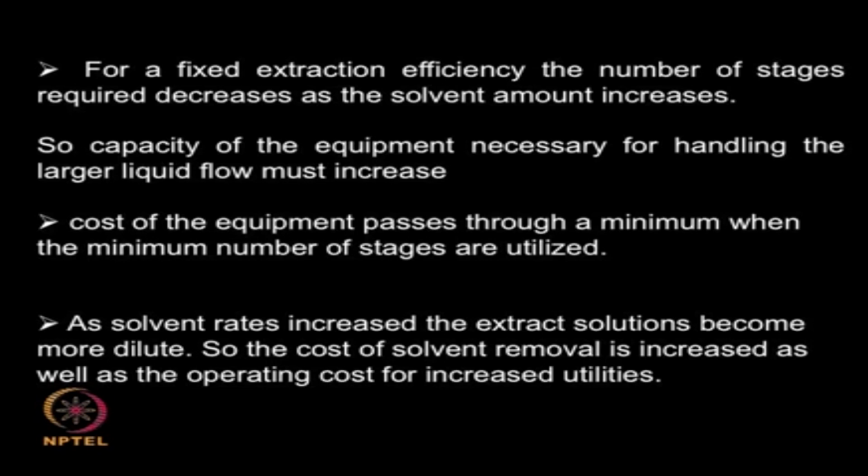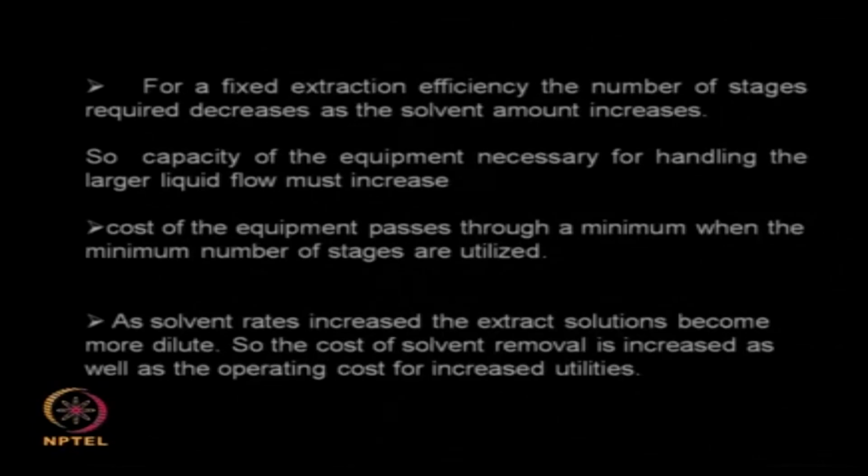So, I can balance the number of stages, size of each stage and solvent amount for the same extraction efficiency, but all of them will have different cost angles. So, I need to look at different scenarios, find out the cost of each scenario, and then make a decision for a fixed extraction efficiency.